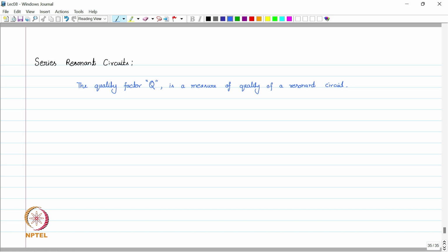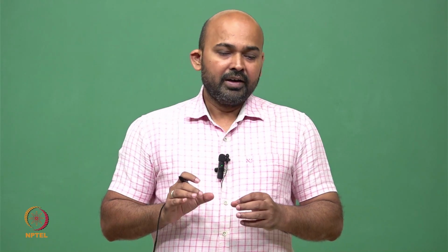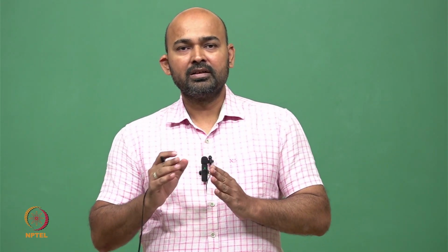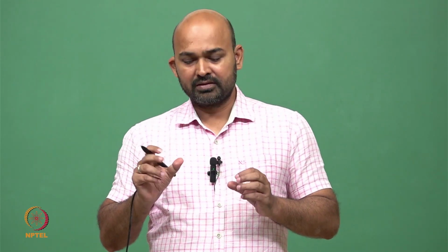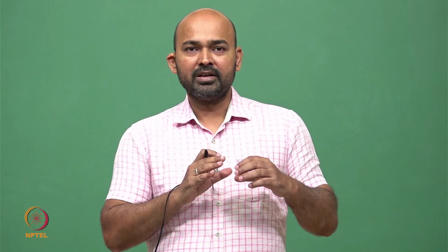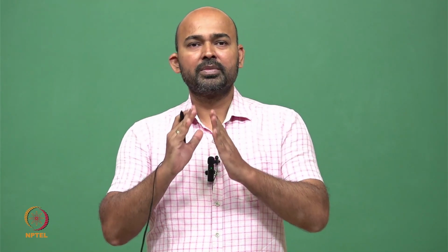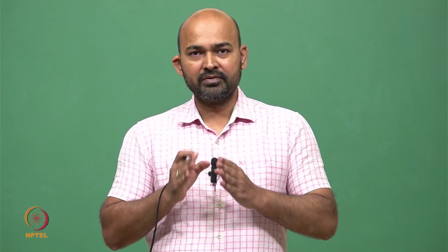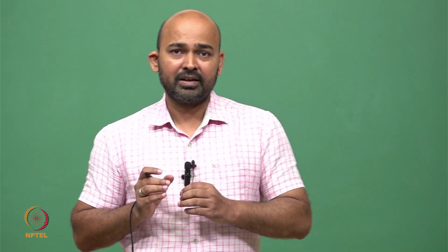So a high value of Q, or the high value of this quality factor, means a narrow bandwidth of the circuit. When we excite this electrical circuit, because the Q is higher, we have a very sharp response of this resonant circuit at that particular frequency where the quality factor is very high.